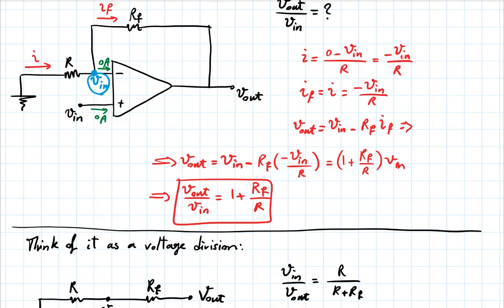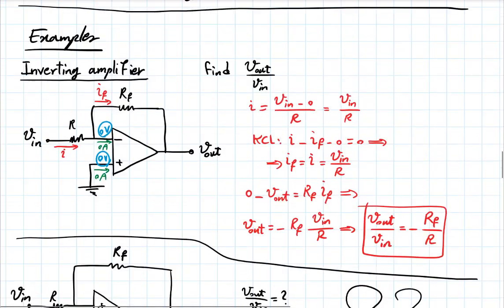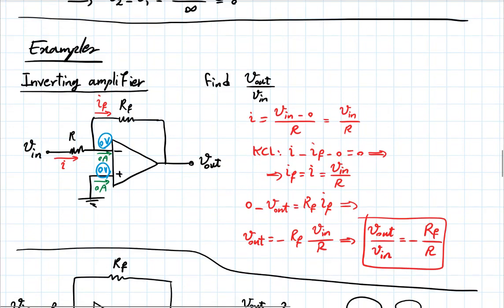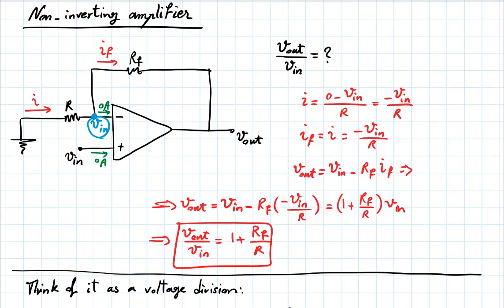And we said that for now, let's assume it's operating in the linear regime. So it has a gain of infinity, and the output is a finite value. That will require that the two inputs have zero difference in their voltages. That will be imposed by the circuit, which means then if this input is at Vin, the other one must be at Vin also. So I concluded that from the operation of the op-amp.